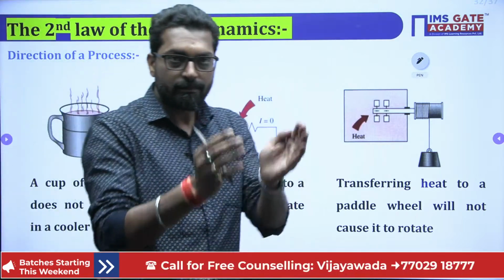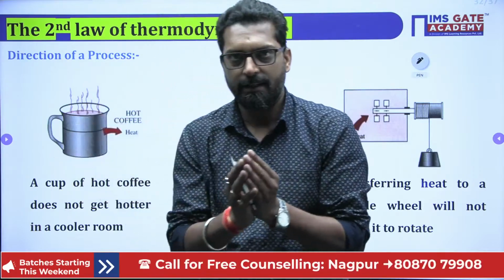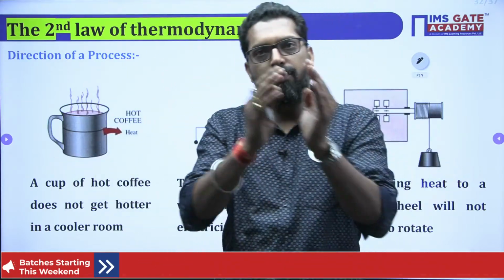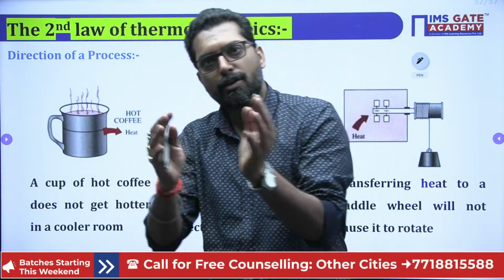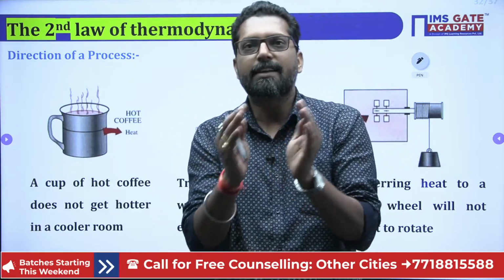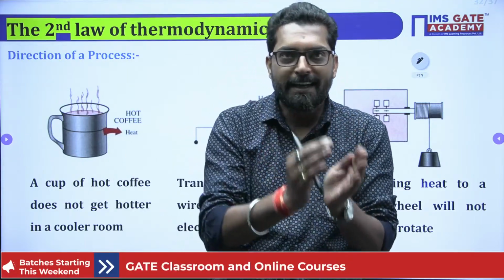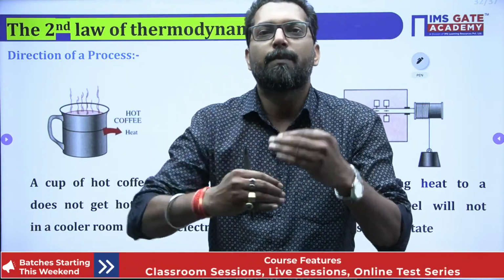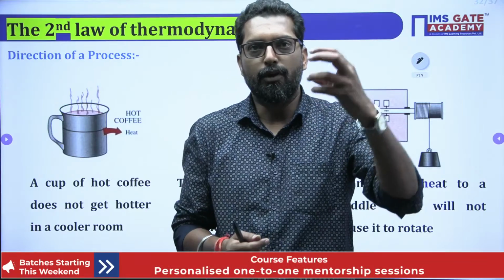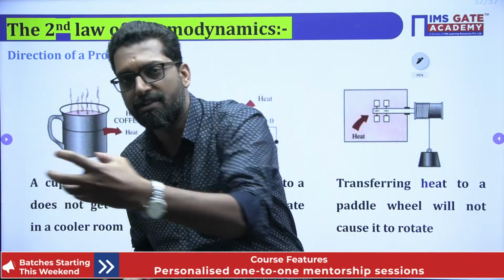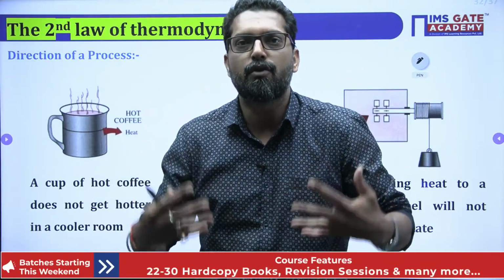We know that the first law deals with the conservation of energy, for the closed system, the open system and the transient system. In the closed system, there is no interaction of mass, so energy interacts only in the form of heat and work. But in the open system, energy interaction also takes place due to the mass of the fluid flow. When mass of fluid flows into or exits the system, the fluid itself has a stored energy.